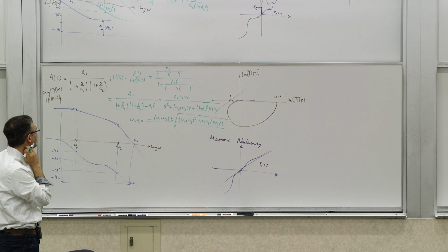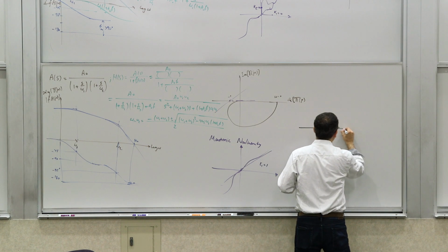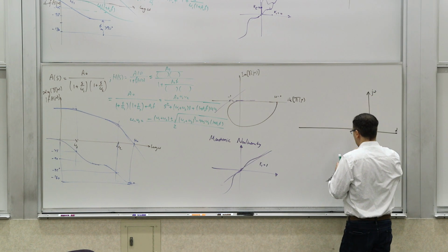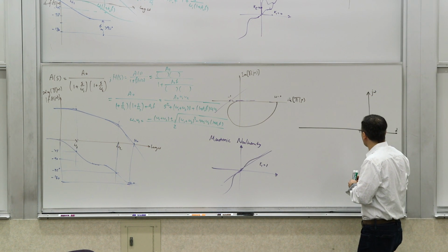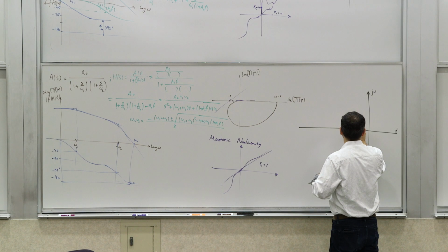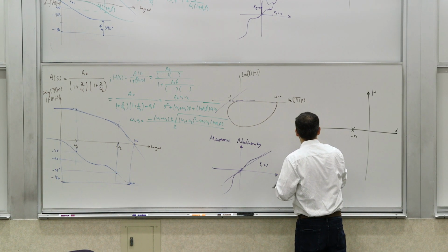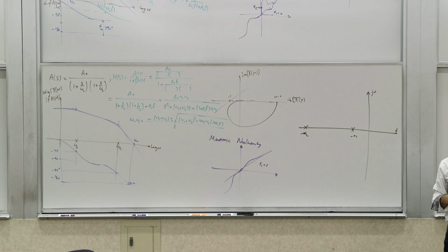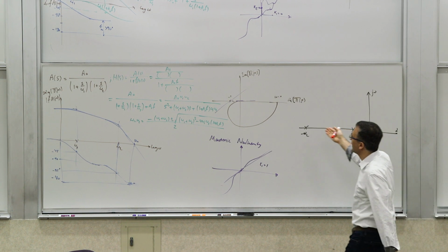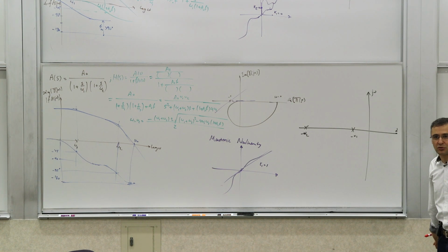The key question is that you can see you're starting with real roots. So if you start looking at where the poles are and how they move, this is the sigma and j omega plane for the poles of the closed loop transfer function. You have two poles: negative omega 1 and negative omega 2. Those two real poles are where f is 0. If you set f to 0, this reduces to omega 1 and omega 2, the solutions, which is where they should be anyway.